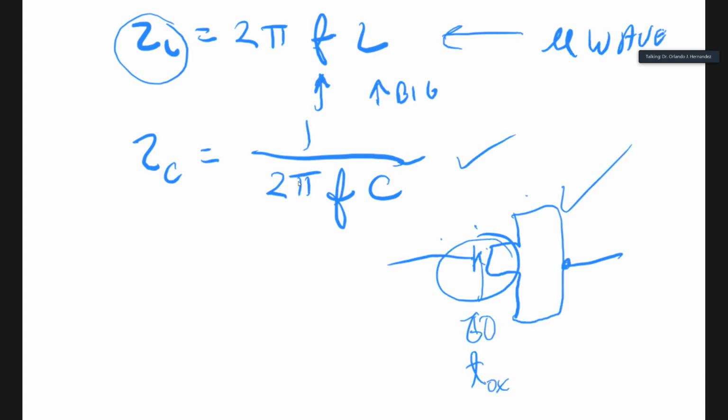To trade off getting rid of this bulky metal-based guy, we have a much more complex type of simulator or simulated inductance based on op-amps and other components. By the way, you can make inductors with fairly decent quality, but for high frequencies, with semiconductor technology, because we do have metal layers, but again, for normal frequency below 1 gigahertz, it doesn't really work.